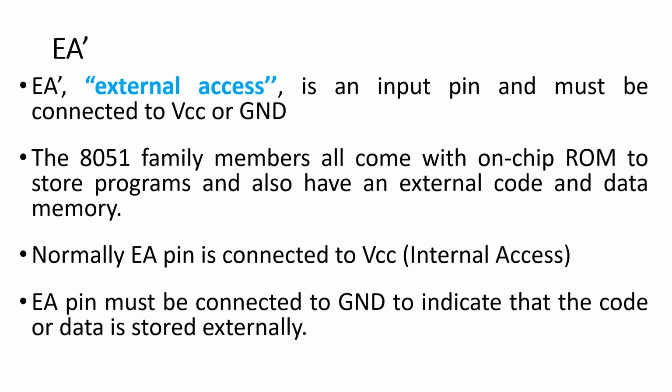We have in the pin description one more pin which we call EA bar. EA bar is nothing but external access. It is an input pin which must be connected to VCC or ground. Depending on the pin usage, we make EA bar enable or low.